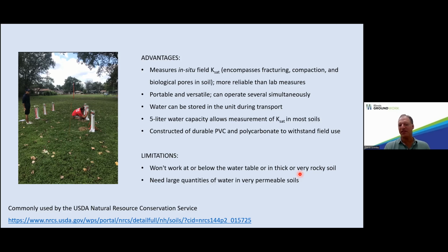The limitations are that it won't work at or below the water table or in rocky soil where you can't hand auger. And you need large quantities of water sometimes in very permeable soils.